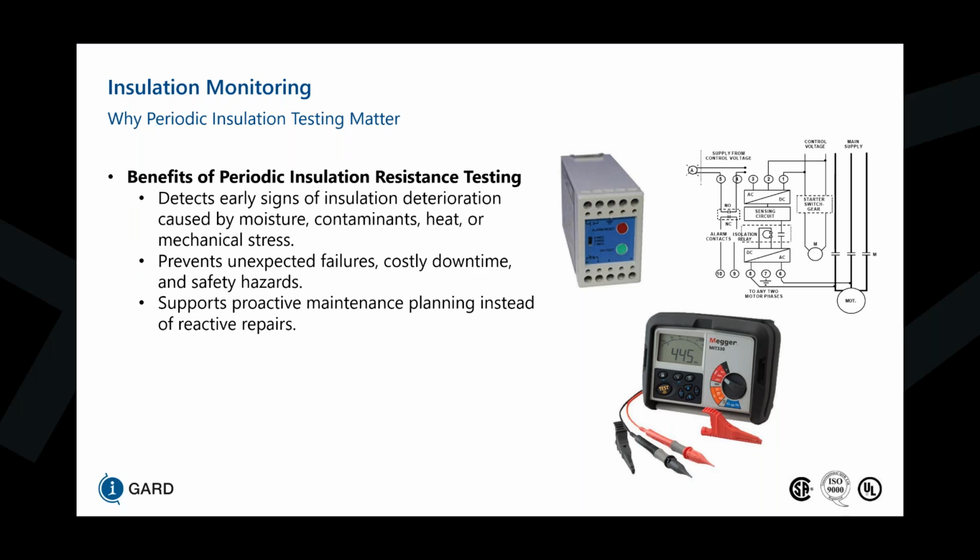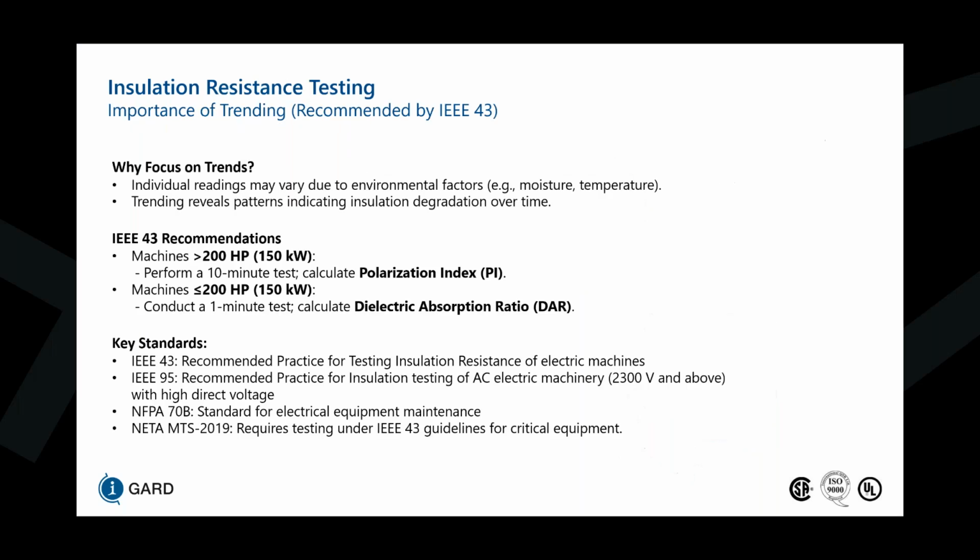So the importance of trending, as recommended by IEEE 43, is that individual readings may vary due to environmental factors such as moisture and temperature. And by doing multiple readings and providing trending analysis, it reveals patterns indicating insulation degradation over time.